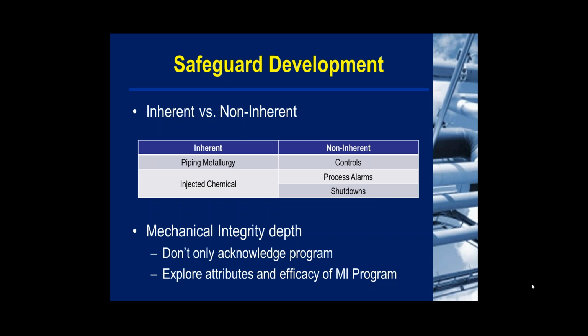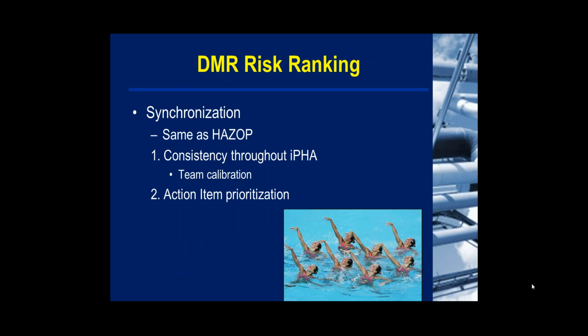Okay, so as far as implementation, our proposed method includes a worksheet that's analogous to HAZOP as well. And what you'd classically see in a HAZOP as a deviation column, we have as the DM node, which includes a short description and the operating parameters involved. Within each DM node, you have different causes, or the way we title them, damage mechanisms. Each one of those damage mechanisms should be looked at from a consequence perspective, and the consequence will follow exactly the same defining characteristics as you would in a HAZOP, which is number one, full description of the ultimate potential consequence, two, a global analysis looking at any effects upstream and downstream, and then lastly, omission of safeguards.